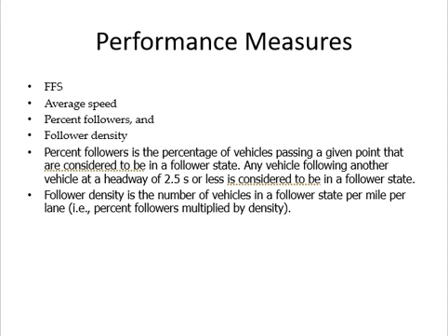Okay. To know the level of service for 2-lane highways, I need to know these things. What is the first one? You already know, right? What is the first point? Free flow speed. Okay, so we already know about it. We have seen some equations. I believe there is a different equation here for free flow speed. Average speed we also know, right? Average speed of the vehicle. Now what is the difference between free flow speed and average speed? Free flow speed is when the traffic is low. And average is normal.